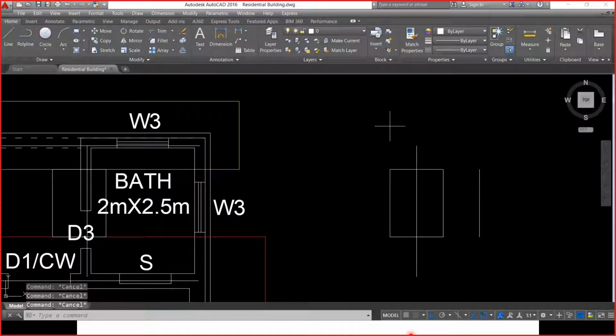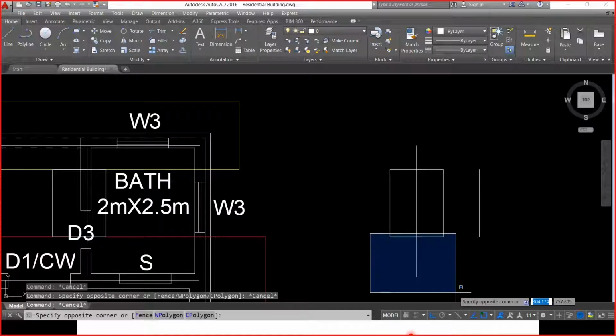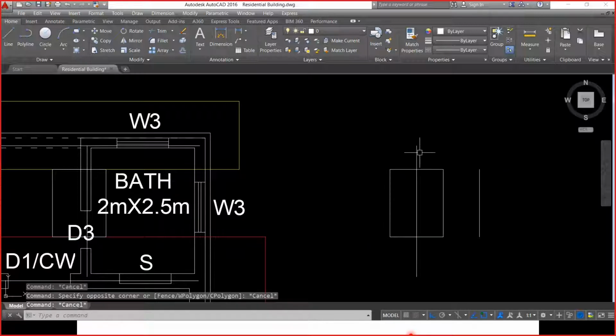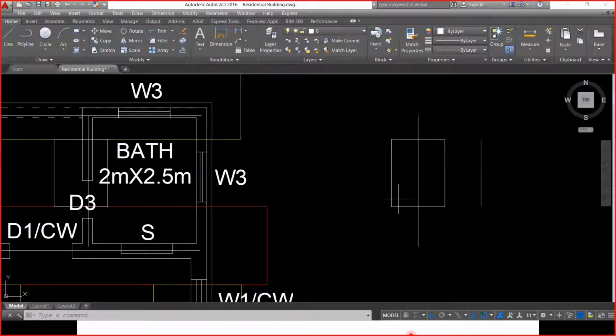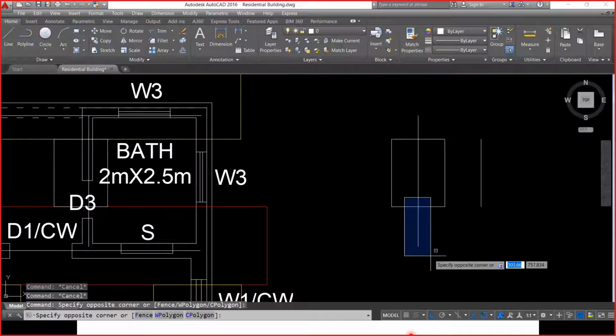In order to calculate the actual length, subtract this much and subtract this much. So what is this? This is 0.6 by 2 because it remains same. It is overlapping with 0.6 meter on the right hand at the top. And when you consider the bottom area, it is going to overlap with 0.5 meter area, not 0.9. It is going to overlap with 0.5 meter area.